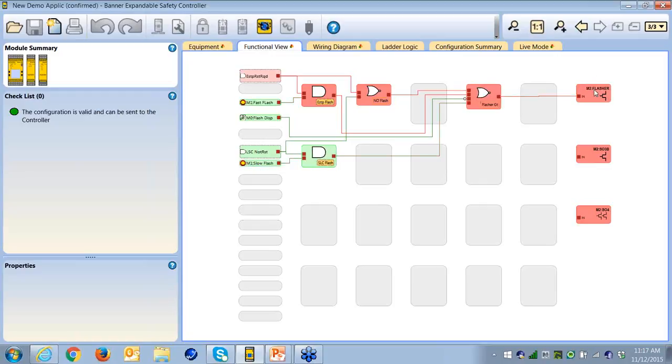Again, all I'm doing is turning a terminal on and off, which I call slow flash. I have two long on and on delays on the other one. That's another terminal. I just have a shorter time on each. I can run them both together, which really looks interesting because then I have multiple flashes, because both of these try to drive it on and off based on their time period, and I get sort of a stroboscopic effect. Obviously, the better solution is to set up the code so that if I have multiple requests, only one of them at a time is decoded to the flasher.